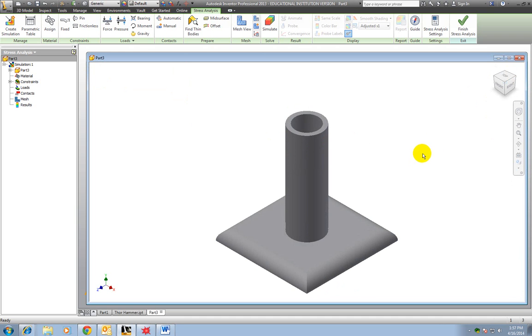So that's one of the first things you have to do, is pick where that fixed point is going to be. Now I'm going to add force to it. I think I'll say that force is being added right here, where the flag is kind of bending and moving. And then I have to decide which direction. Either direction is fine; I'm going to leave it the way it is. And I'm going to decide how much force is actually acting on it.